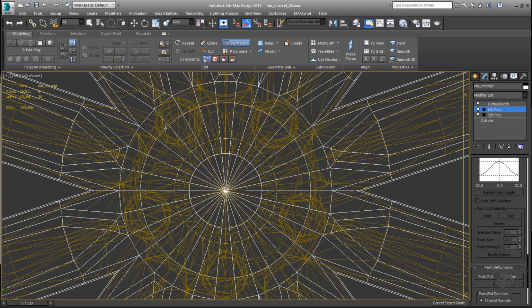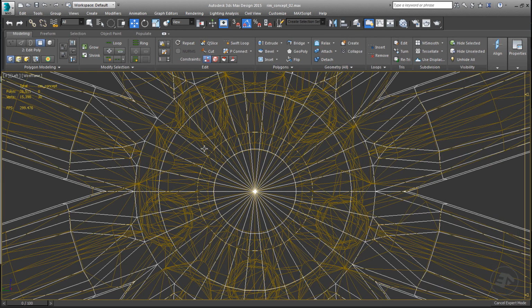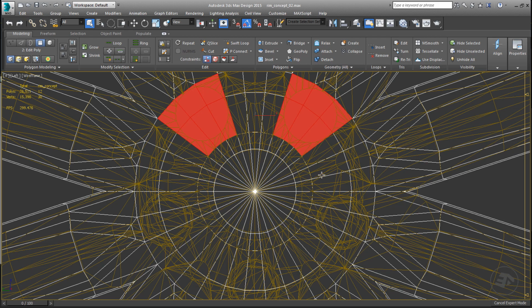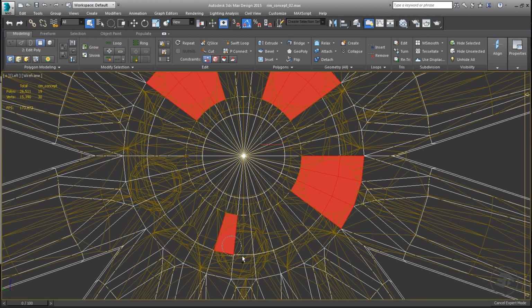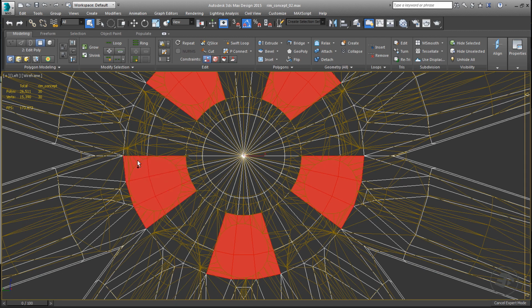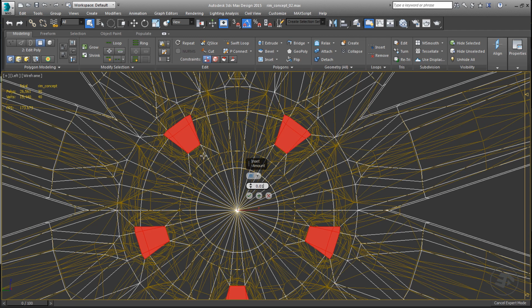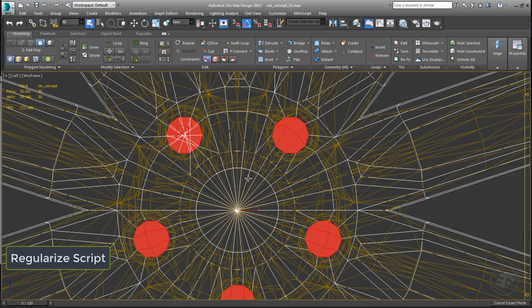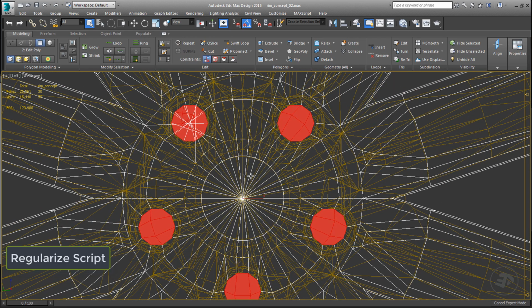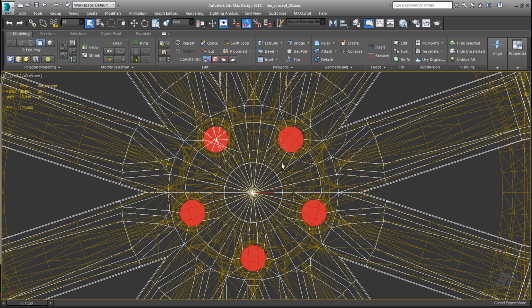Try to offset the supportive loop away from the center a little bit. Change the inserted amount to 10 mm. Hit relax on the ribbon to relax the selection. The obstacles never end.